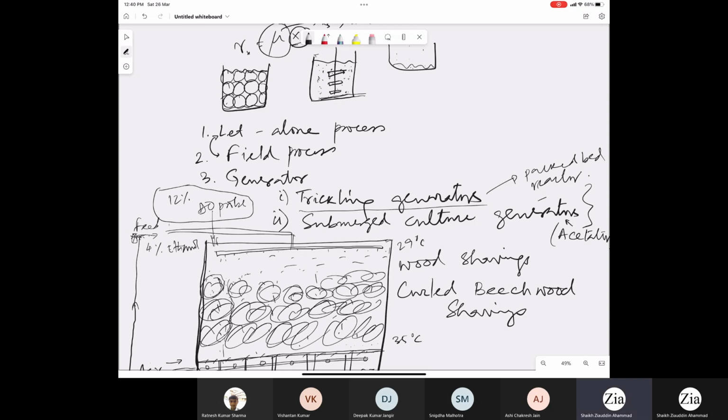The only difference is that the control is much more intense, and you can have a much higher conversion rate. So you can have higher productivity in this system. And if you compare the volume, to produce the same amount of acetic acid, you will need a much lower volume of reactor. So the reactor footprint will have a significant size reduction when you use this submerged system.